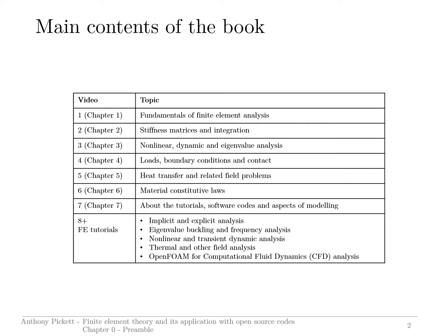The tutorials themselves do use a variety of different materials, so I thought it would be useful to have a chapter dedicated to material constitutive laws. This could be a book in its own right, so I've only concentrated on 3 materials. Elasticity for isotropic and orthotropic materials, so the sort of material laws that you would use in composites analysis, for example. I then go on to hyperelasticity, which you would use for rubbers and polymers, and finally plasticity laws.